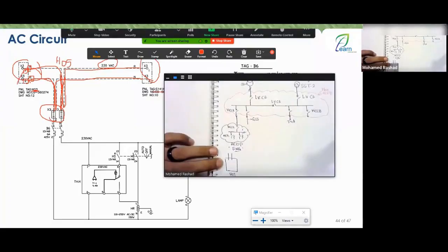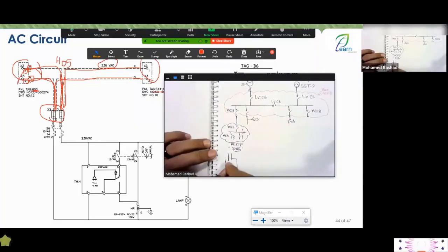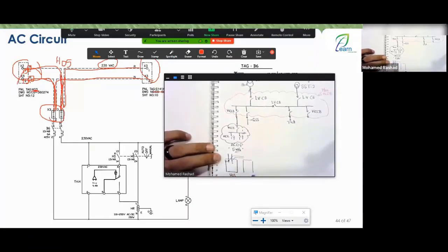You then connect them to the first switchgear cell, which is supposed to be named H01, for example. Great. You then connect here to the terminal block, which is our junction box, for example, X3, numbers 1 and 2. After that, you exit from this same terminal block and go to the next cell, connecting again to terminal block X3, numbers 1 and 2. And then you exit, then you go to the next cell. For example, 805, 803, and so on.